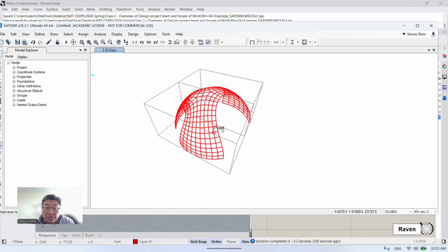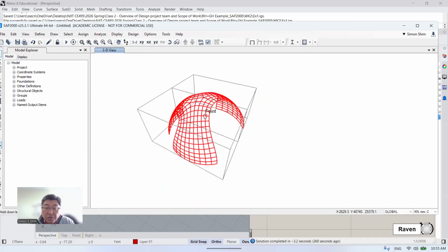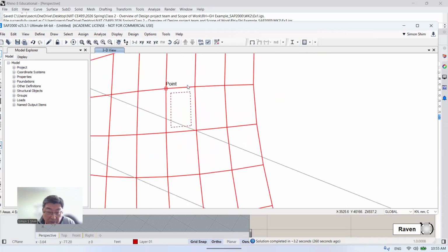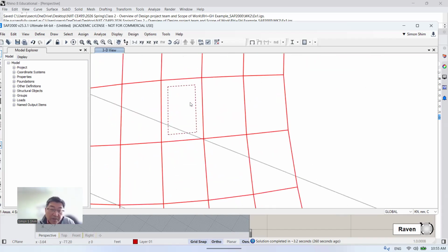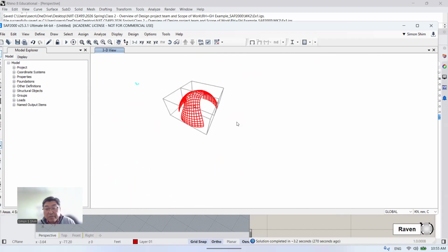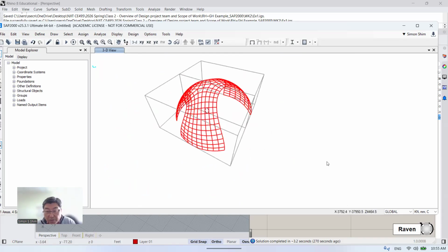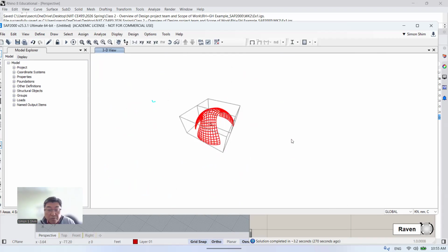What we're going to do is I'm going to show you another triangular mesh. A rectangular mesh like this, we call rectangular, it's quadrilateral elements. And we're going to create another, triangular mesh. So we're going to import two models. And once we import two models, we're going to start assigning some loading and set the boundary condition. We can analyze this structure based just on the self-weight of the structure.